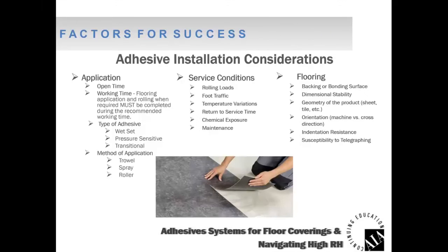Adhesive installation considerations. I don't want to spend a whole lot of time here. We certainly could, but we've got a lot to go through. But I just want to make sure that you understand what we have to keep in mind when we're looking at selecting adhesives and floor coverings and building an installation system. Certainly open time. There are adhesives that are two component that you drop in as a wet set immediately. Even the single component wood flooring adhesives, no open time, but your waterborne adhesives in most cases require an open time, maybe 10 minutes, maybe 15, maybe 20, allowing some of that water to flash off.